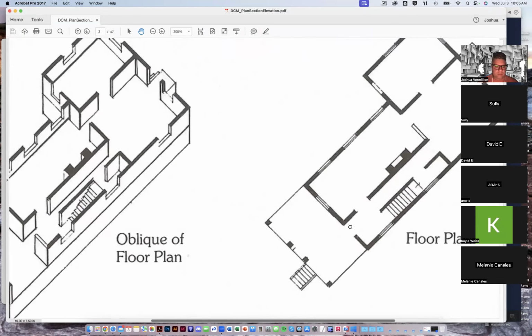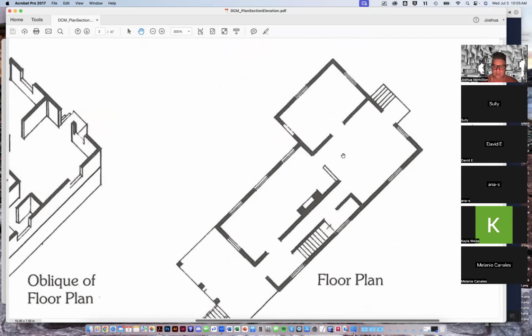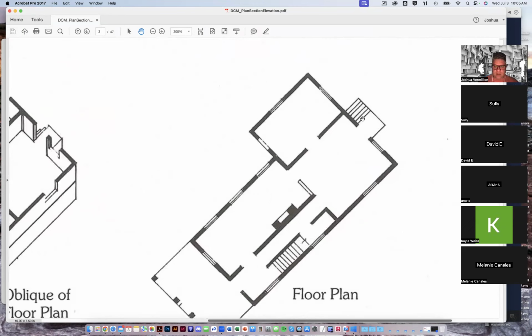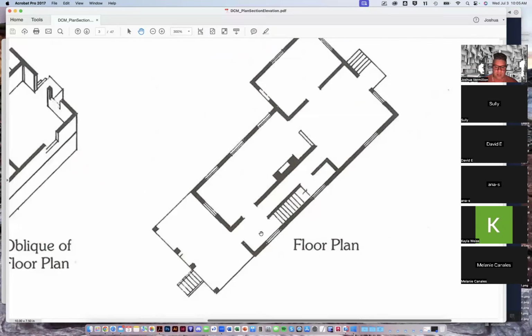Here we have what looks like a chimney or a fireplace, and the flue going up. It's being cut, and you can see the hearth just in elevation below. Of course, we also can show stairs in elevation below. Here's the stoop with the staircase going down. Here's a staircase going up from the first floor to the second floor. At the 4-foot level, we add a little cut mark and then discontinue the staircase, letting us know that the stair is going upwards, that it gets cut at 4 feet in the plan, and that it would continue up to the second floor.